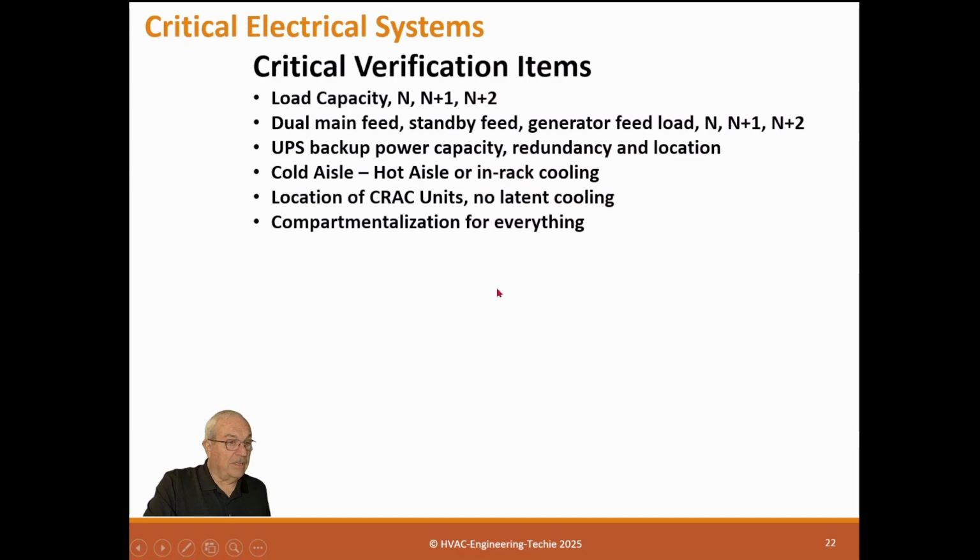Compartmentalization for everything, so that if we have a problem in one area, it's not going to affect another area. And what that means is, if you have a switchgear room, you need a separate switchgear room for the redundant side, because if you have a breaker blow up, it's going to take that room down, so you have to have the other one available.